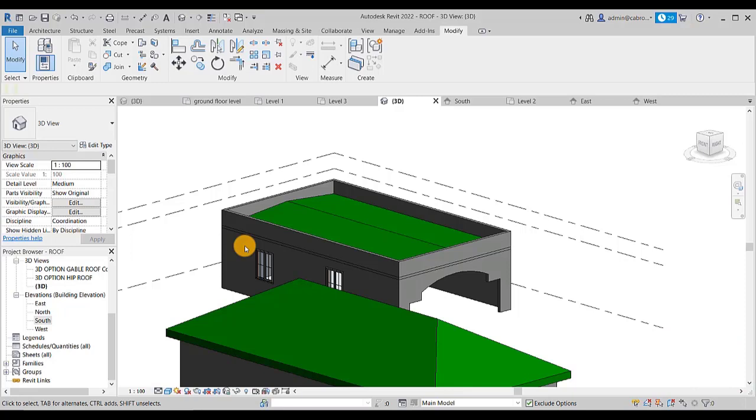And most of the stuff which we have in Revit, we model it using that generic means. So let's see the options available to us. Then we'll try extrusion and sweep, because those are usually for the external models. Okay, external generic models. The rest that we will look at, I will discuss very soon. Those will be for modeling of objects, so those can be used when we are doing component modeling.